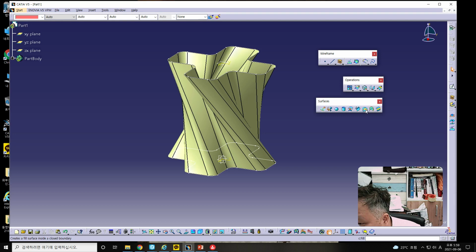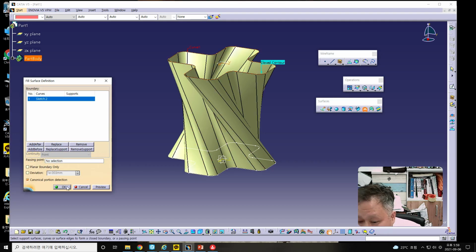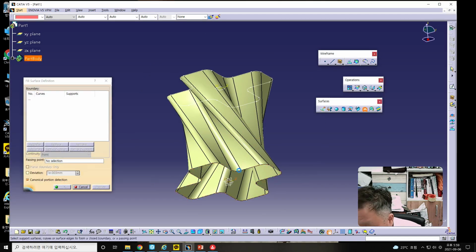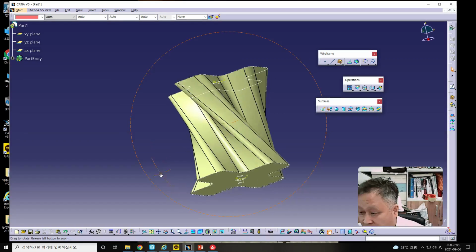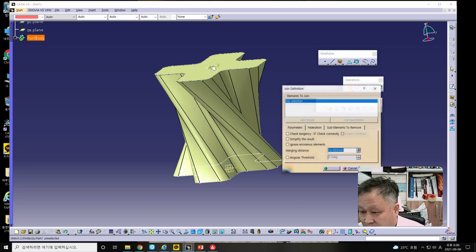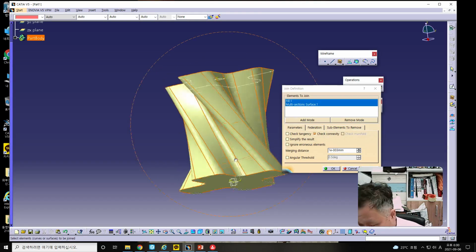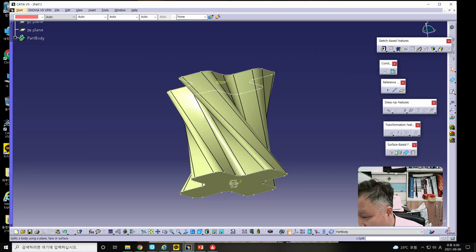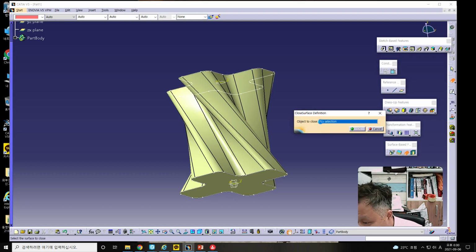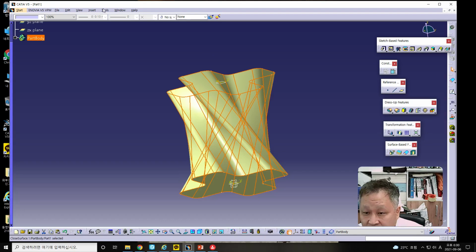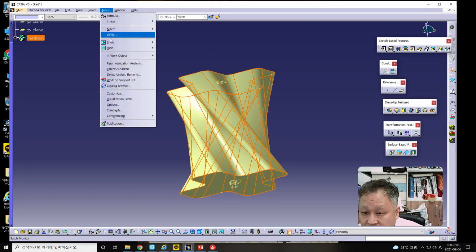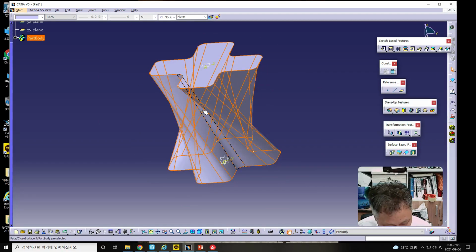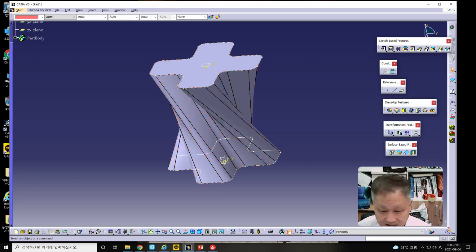by using the fill surface menu, the upper can be filled, and also the bottom can be filled from this bottom, and by using the join menu the 3D surface can be joined automatically from this, and go to the Part Design workbench and fill surface and select Join.1, then please hide all the surfaces from this button, and a new closed surface can be made like this.